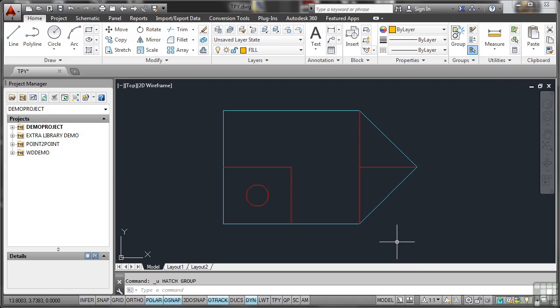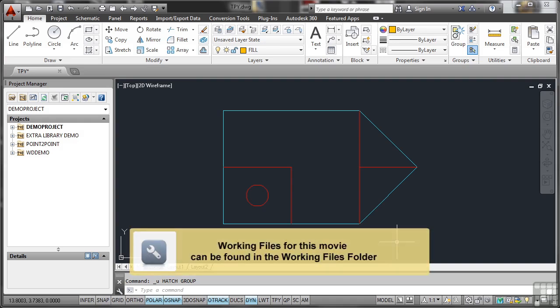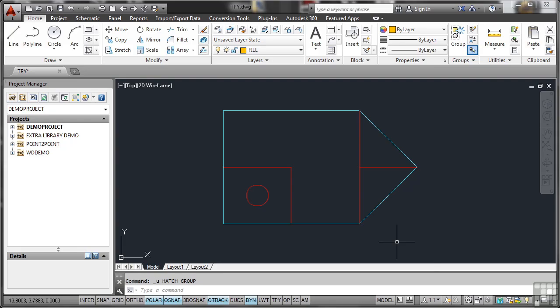When you're working with AutoCAD Electrical and you're creating perhaps schematics or panel views, anything in AutoCAD Electrical, you might want to use something like a hatch or a solid fill to highlight an area on a drawing. The drafting setting TPY here, transparency, actually allows you to hide or not hide any transparent objects. I'll just switch it back off again for now. So let's go now and place a hatch on this area here where the circle is.